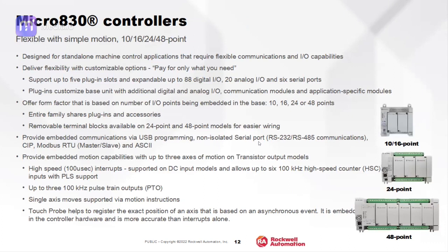And then the inbuilt serial port is non-isolated. Within the Rockwell controller, you can configure serial. If it is third party, you can configure Modbus RTU, either slave, and ASCII also it supports. The controller comes with a removable terminal block. We can easily do the wiring.